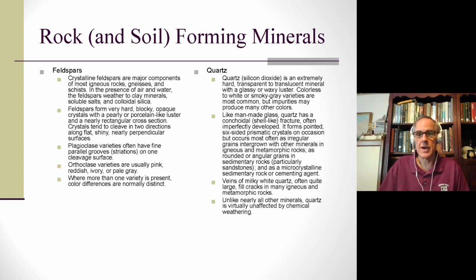But the most common appearance of quartz in soil mechanics is in sandy soils. Generally speaking, most sandy soils are what we would call silicaceous. Since it's silicon dioxide, quartz, any soils which are based with quartz particles are silicaceous. They are virtually unaffected by chemical weathering, and they're very difficult to break down with chemical processes.